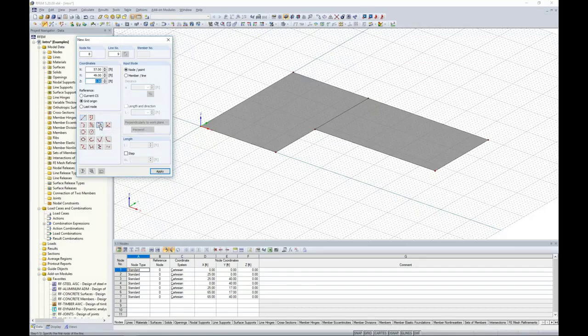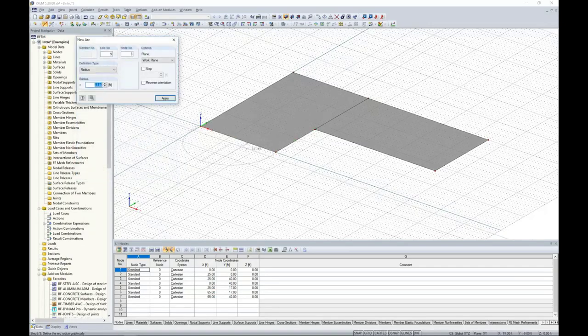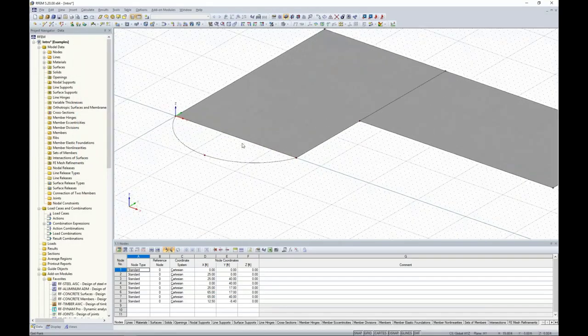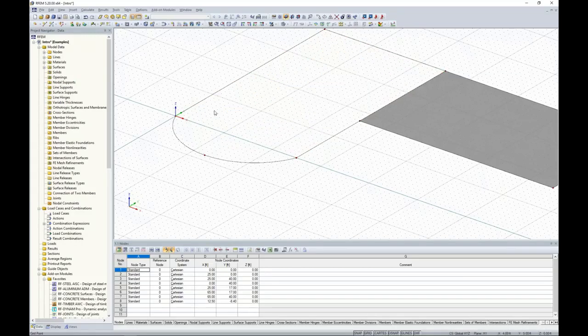We will select the arc, and we will click on the left point of our slab on the left to the right point. Now, my third click can be anywhere within the project grid here to define my radius, or I can simply type in 13.5 feet on my keyboard for my radius, and I hit enter. And so now you can see that arc was generated here. So using my selection box, I can highlight only the front line here and the surface. I hit delete on my keyboard and I'm left with the exterior boundary lines.